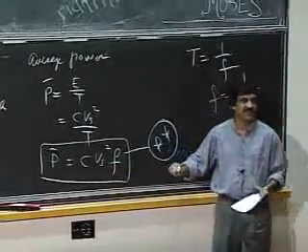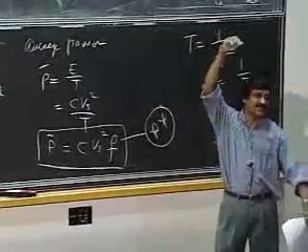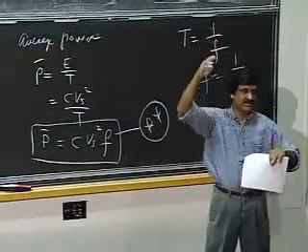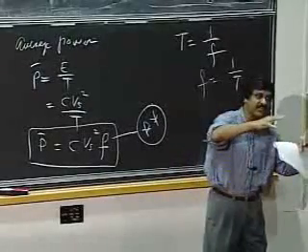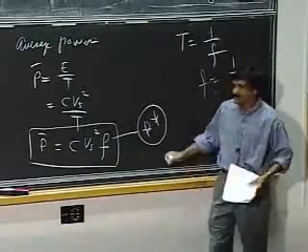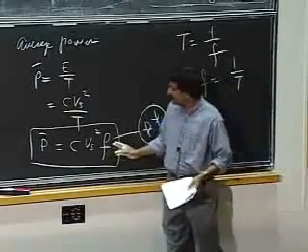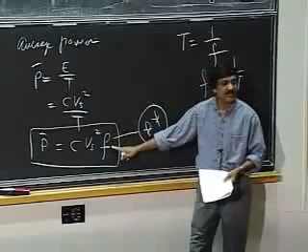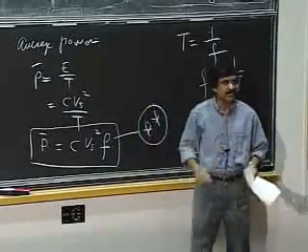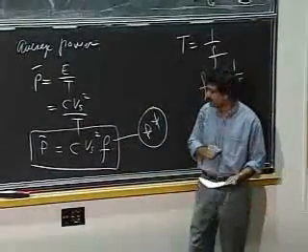Notice that at any given time, there is no direct connection between the power supply and the ground. What I'm doing is my capacitor is an intermediary. I'm dumping some charge in the capacitor, and the capacitor is dumping the charge into ground. It behaves like a switched capacitor, and it's being charged and discharged at frequency F. So it makes sense that the average current that I'm pumping through relates to the frequency at which I'm charging and discharging the capacitor.